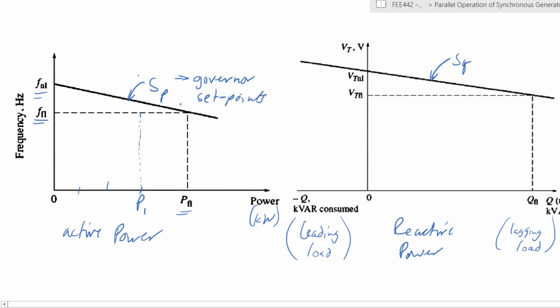Under the set points that we give in this, that result in this slope, your full load power will be at a frequency of here, FFL. But if you still want to have that frequency, but supply active power at a lower level or even at a higher level, you would then need to change the set points, and you would have a line that goes slightly like that. Okay, my line is not very accurate. Try again. Close enough. Okay, so what you would do is you would then have a new value of no load frequency at which you would set your governor.